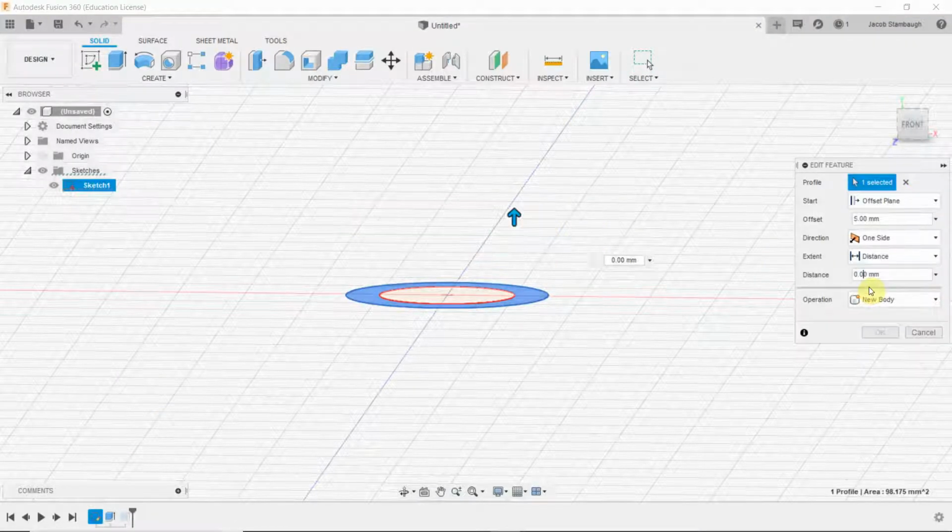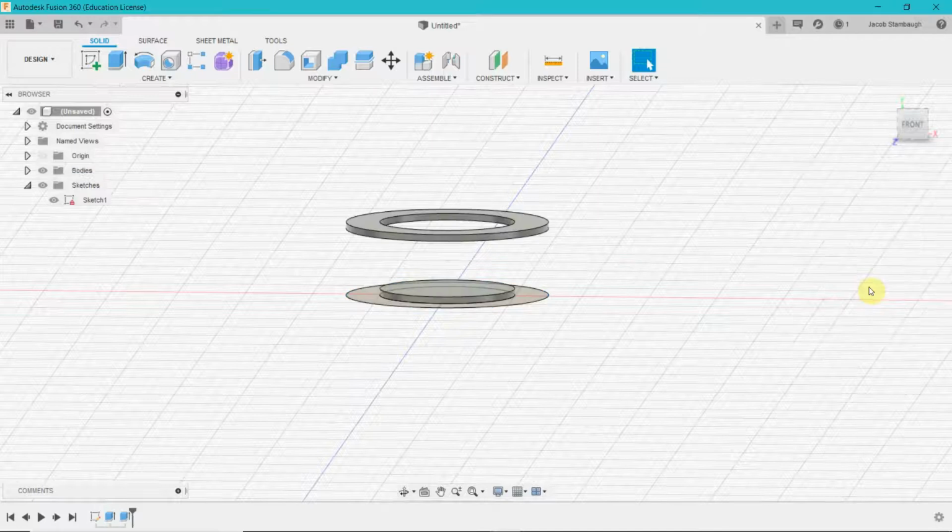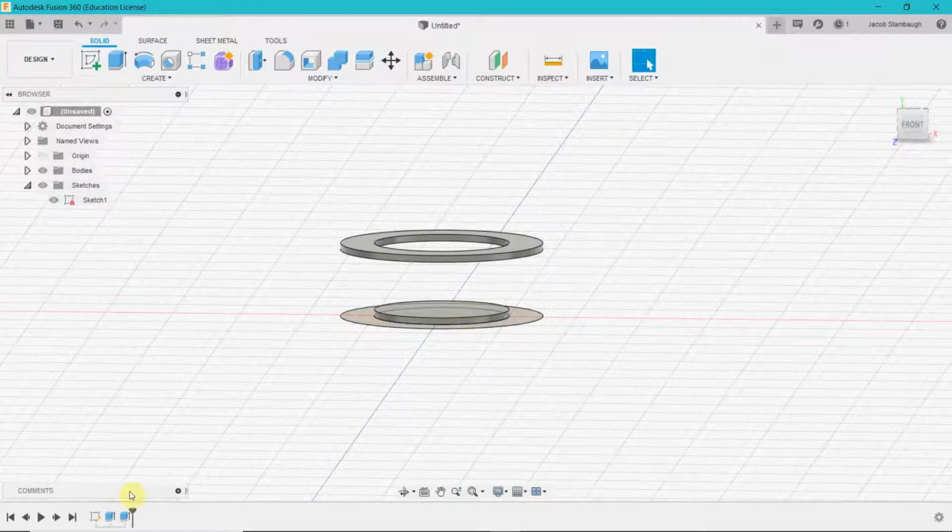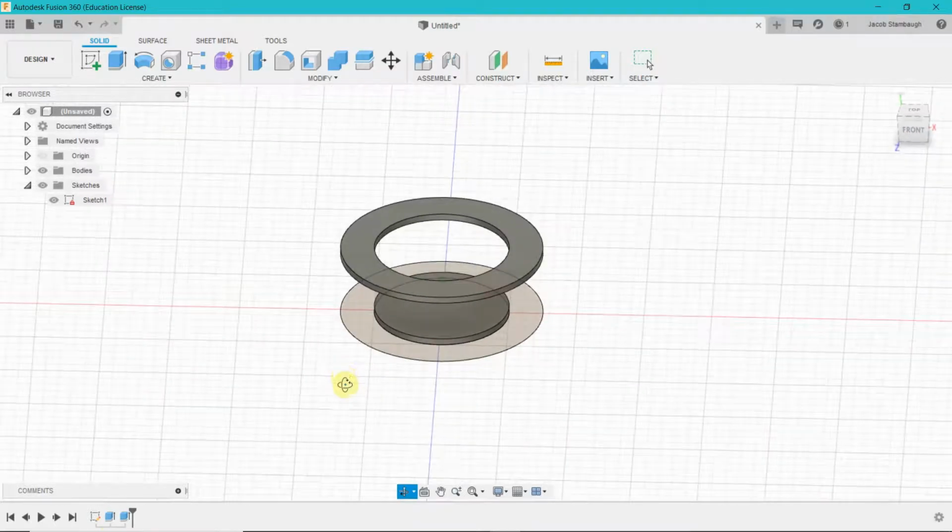So in this case, I'm gonna make this 0.05 to match the plate. And one really useful thing about the timeline is anything you edit behind where you're at in the timeline automatically corrects everything else you've done from that point. So let's say I created some circle here and I put another sphere or something based upon the geometry of the first circle we drew. Autodesk will automatically correct all geometries created from the initial one. That's something really nice that it does.